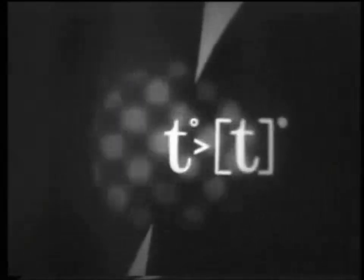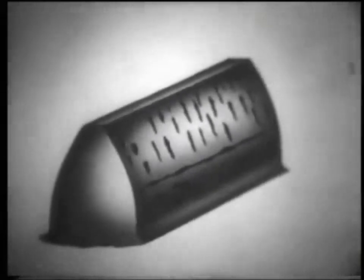Pieces of metal break out of a softer surface and firmly grasp a harder one. When rolling with sliding on a paired tooth, they furrow its surface. This form of jamming is called scoring. Abrasive wear is a type of damage characteristic of open gears or gears that are poorly protected from contamination.